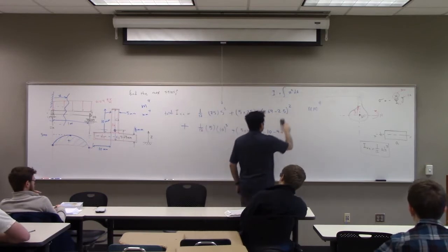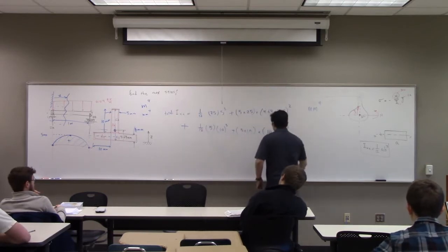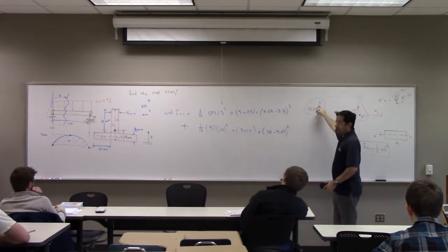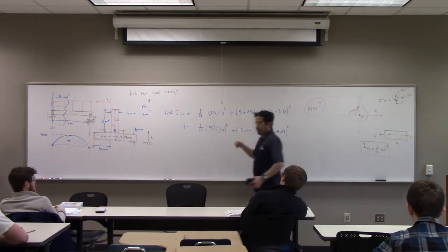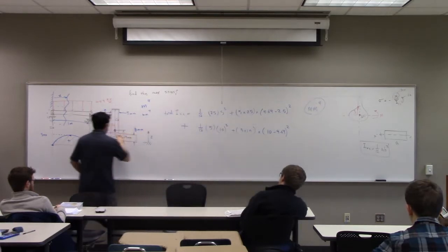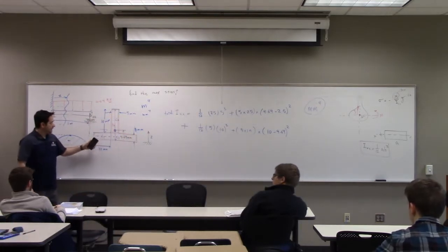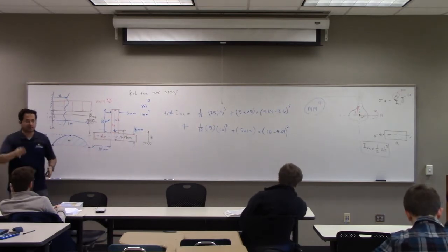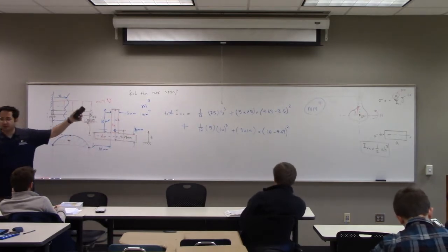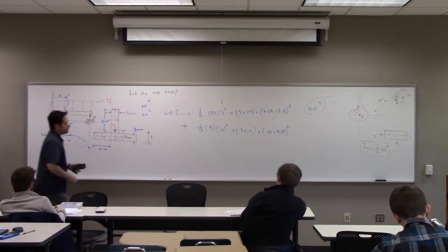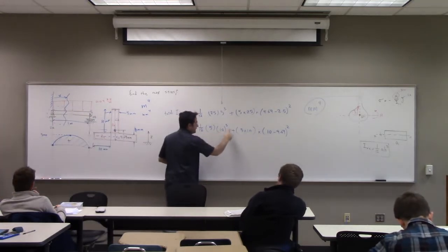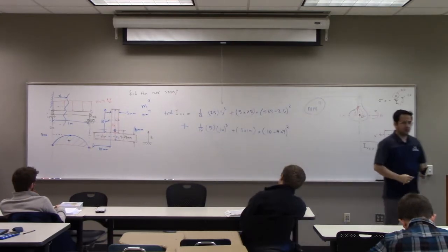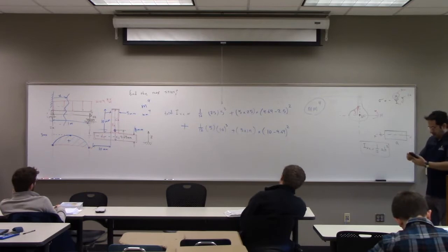So the entire summation I'm going to get is in millimeter to the fourth power. Why millimeter now? Because for the dimensions that I use here, everything is millimeter. So I'm just consistent. I expect the end result in millimeter to the fourth. You could put a 10 to the negative 3 everywhere here, but that makes the expression very long. So let's continue.